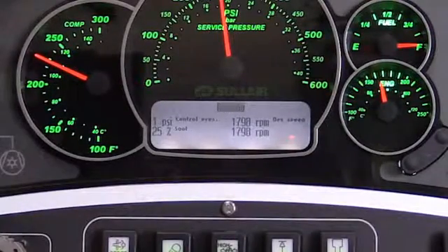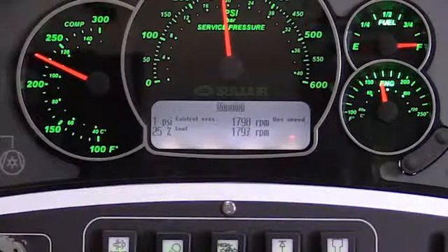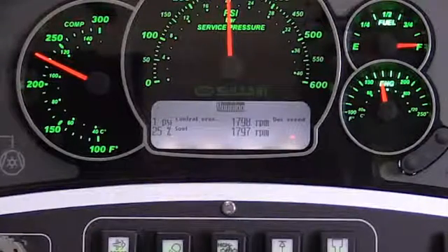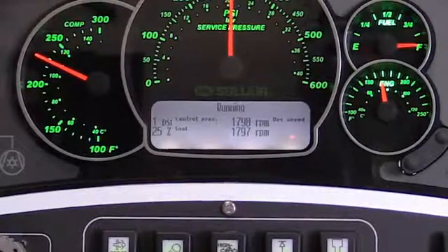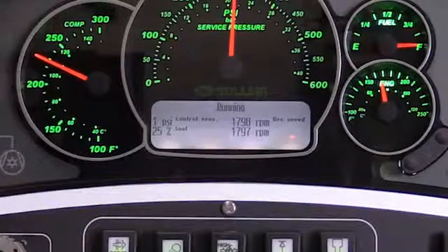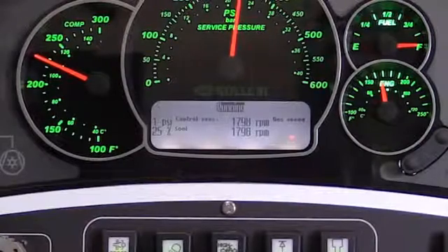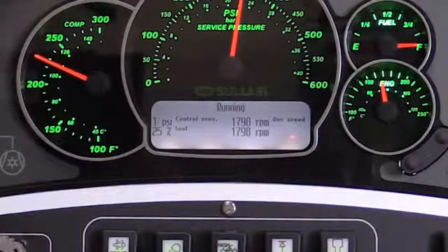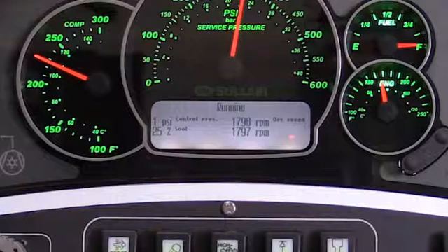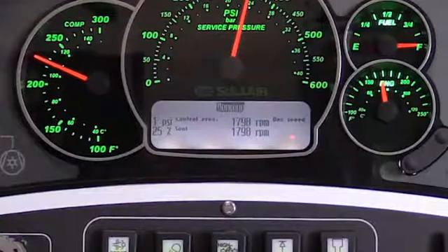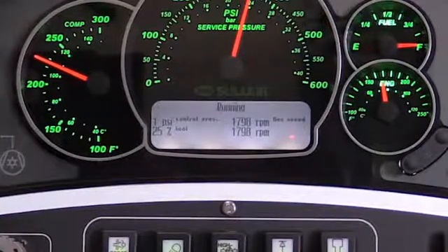Shown here is the fully loaded state. Ball valve is just open far enough to drop control pressure down to 0. This means there's no pressure at all going to the closing feed port and the inlet should be completely open. It also means there's no pressure on P2. C-Pro sees this and adjusts the desired RPM being asked from the engine accordingly. What this all means is that the inlet is completely open, engine is at max RPM, and the machine is fully loaded. We are now at full capacity.